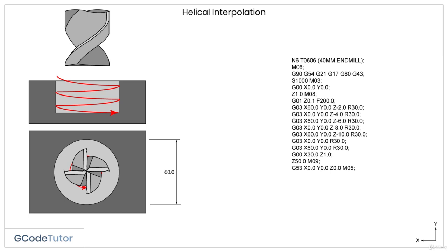One way to tell the machine to go back to its reference position is by using G53, the machine datum. We can also use G28 to get the machine to go back to its reference point. M05 stops the cutter. G40 turns off our cutter compensation. And finally M01. This is our M code for optional stop. If the operator wishes, he can push a button on the controls and have the machine stop at this point so we can measure the bore to make sure it's correct.